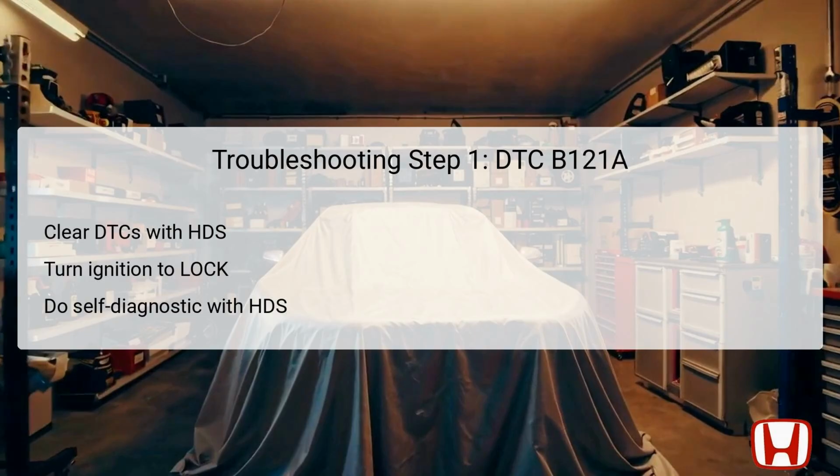Honda Diagnostic System, HDS. This tool is essential for accessing and managing various fault codes in the vehicle's onboard diagnostics. After clearing the DTCs, the next procedure involves turning the ignition switch to the lock position and back to on. This sequence resets the climate control module, preparing it for a self-diagnostic check.